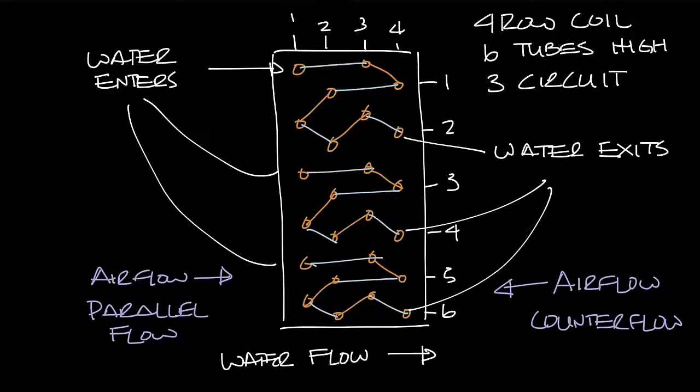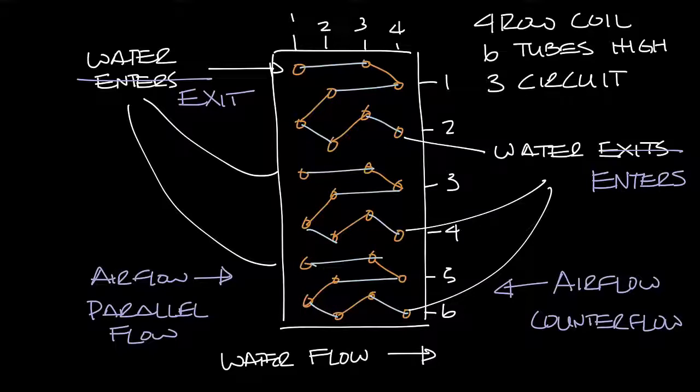water coil. And as I look at this now, I realize that I show the water entering from the top and exiting out the bottom, but actually you want your water to enter through the bottom. So this up here is an exit, and these over here are where the water enters, because you want any air bubbles to float to the top. Okay, now that our drawing's correct.